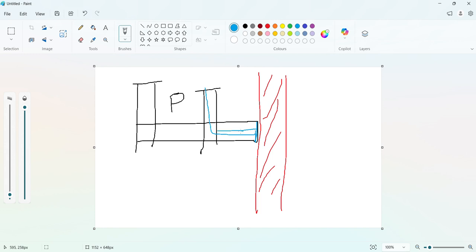So there will be some backflow happening. In that case surcharge will also happen in the previous manhole. To ensure no flooding, we need to decide in that way only. So after the hydraulic gradient, this flow reduces. Consider this as a 500 pipe. Okay. Already this is filled, so there is no water to escape.